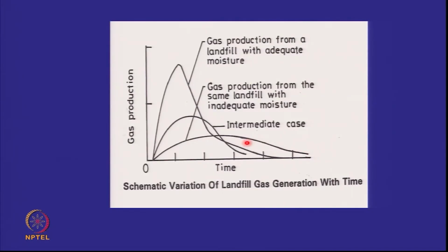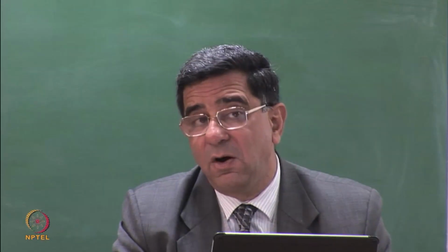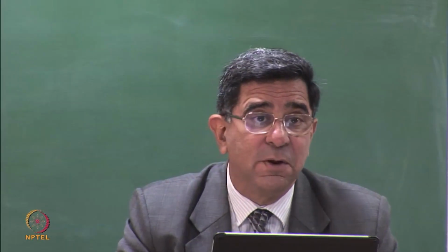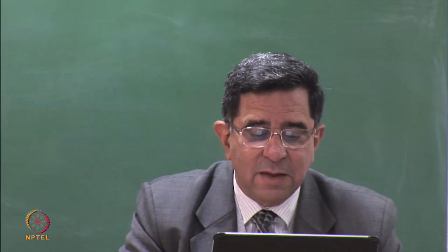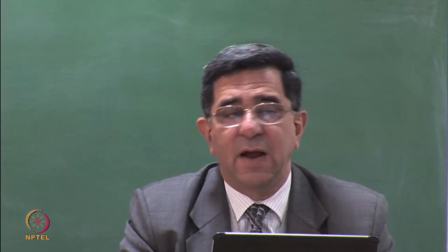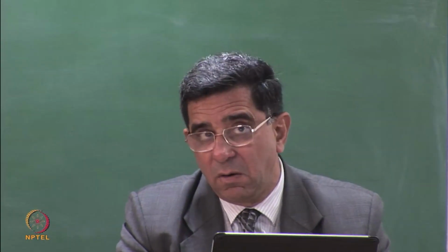So if you have a landfill with adequate moisture and something like a bioreactor landfill where you are recirculating the leachate, it's a landfill with adequate moisture, and therefore it will give you a lot of gas, but it will give you gas for a short period of time. And what is this time that I am talking of? Maybe 5 to 10 years. So a bioreactor landfill may give you a lot of gas for 5 to 10 years or a little more.